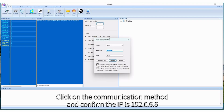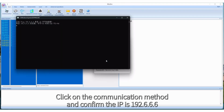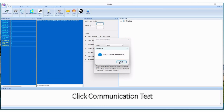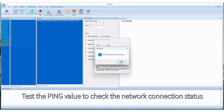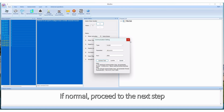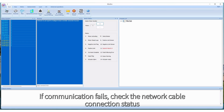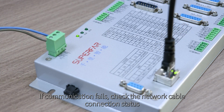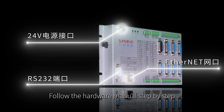Click on the communication method and confirm the IP is 192.6.6.6. Click Communication Test. Test the ping value to check the network connection status. If normal, proceed to the next step. If communication fails, check the network cable connection status.